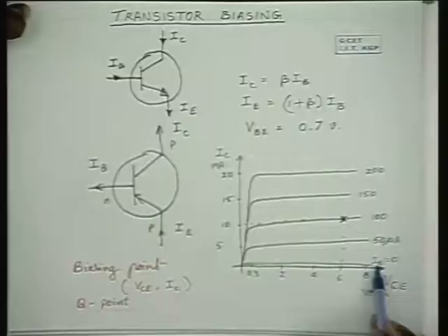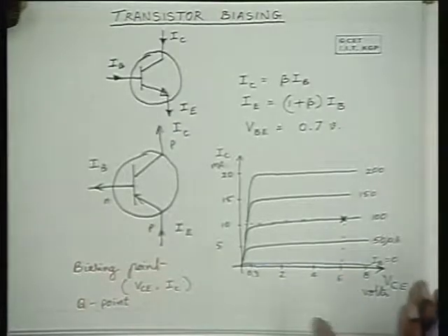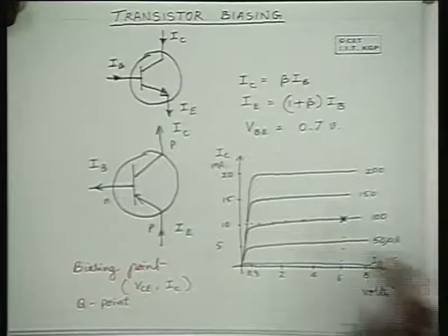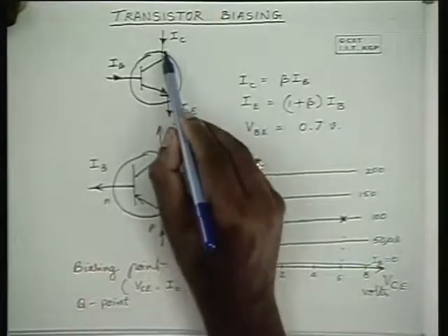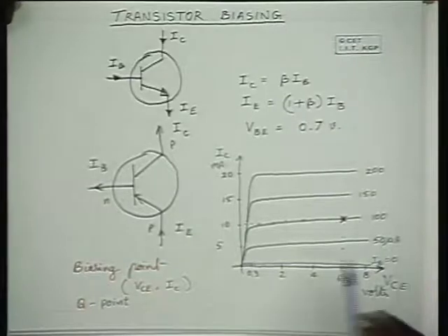0, go below 0. And when the base current becomes 0, the transistor is cut off, collector current is 0, and when the collector current is 0, you will have distortion in the output. Hence the transistor goes out of the linear region, or the active region.